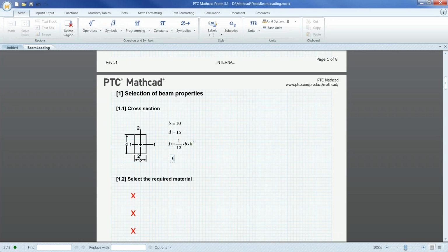So if I type in I equals, which evaluates our expression of I, we get some number with some units attached to it. Now, this is a little confusing because this number is extremely small, which doesn't make much sense, and the units are completely off. Now, H is green, which means it's an actual constant hidden inside Mathcad, which has a bunch of different constants you can use, such as pi, and H happens to be one of those. So we know something's already wrong. So what do we do to resolve this? Well, we can go back to our expression and take a look at it and say, oh, okay, so it looks like I had a mistake here. It should be D instead of H. So if I delete that and add D and hit enter, it automatically will update the results below.